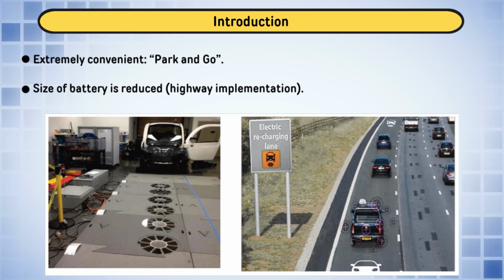And one important thing, these DC-DC converters are helping renewable energy sources so that they can realize constant impedance, because you cannot control the load where the resistance is varying throughout the day. If resistance is varying, your MPPT point may move left or right.